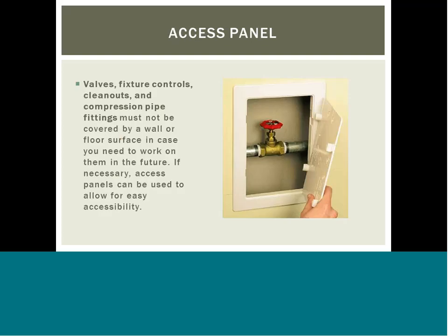Valves, fixture controls, cleanouts, and compression pipe fittings must not be covered by a wall or floor surface in case you need to work on them in the future. If necessary, access panels can be used to allow for easy accessibility.